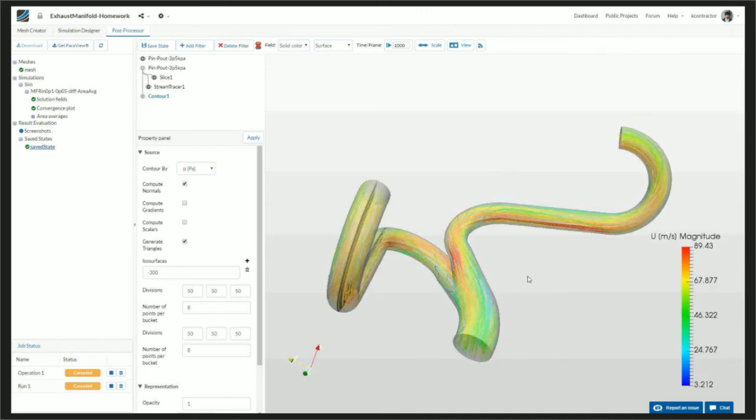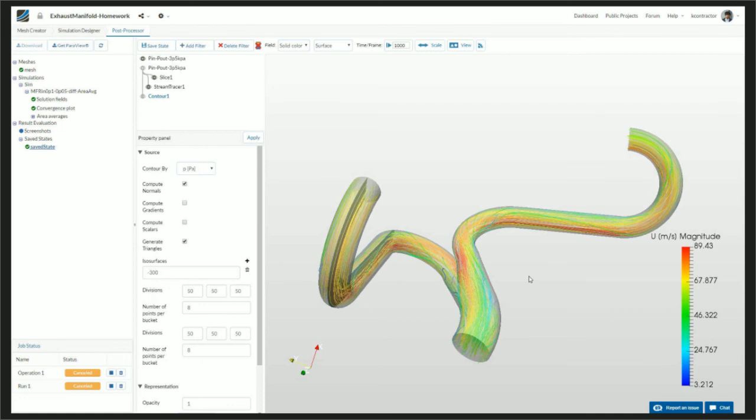There would always be very, very small vortices in the flow, which would be turbulence eddies or small scale turbulence, but that is not the aim of our simulation. We just want to see if there are major recirculation zones which would actually block the flow in a significant sense. So for this operating point, we can say that it's a decent design.